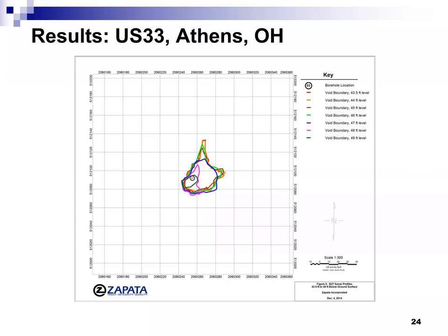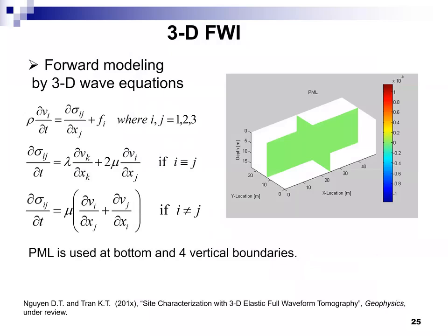In this case, the lateral dimension is large. Total sense, doesn't it? I mean, in terms of the size of the void. Yeah. Just like us in SASW, the thickness of the layer relative to the depth you're at. Yeah. So you see that softer material. Here the dimension is large laterally, that's why we can go down to 50, 60 feet in depth.